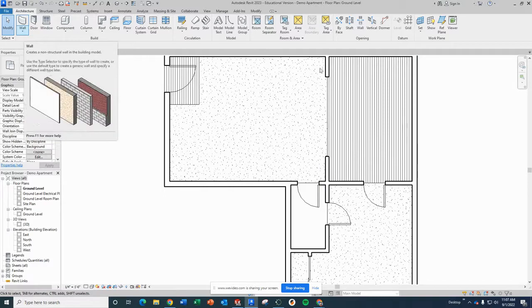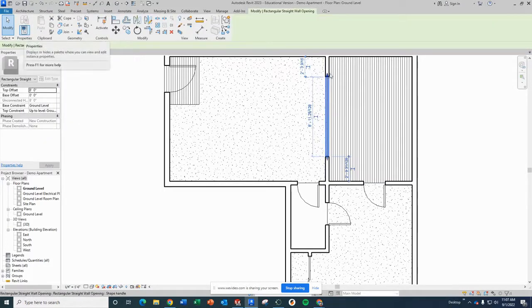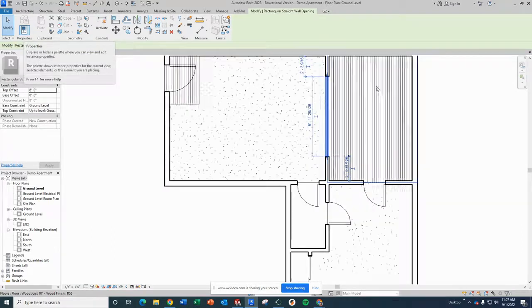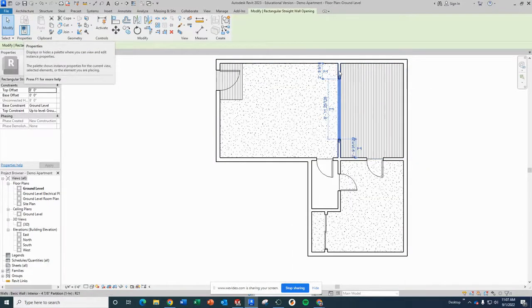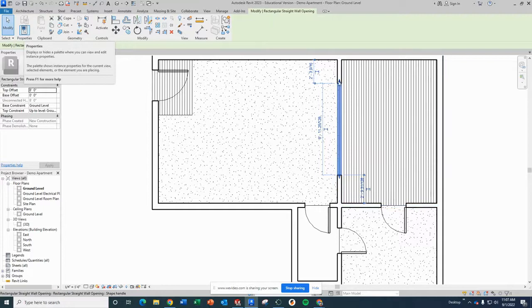Now, it's not just that it deleted the wall. There's actually an element there. So again, just like I can move the doors around, if I put cabinets in here and the wall opening is not covering the end of the cabinets, I can grab this little slider right here, this little arrowhead, and move the opening back and forth. I can move the entire opening. I've got settings for the opening right here.